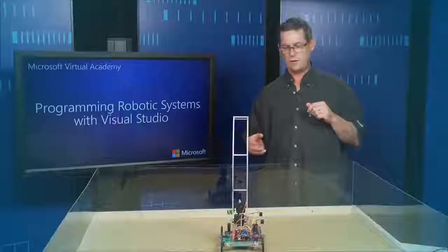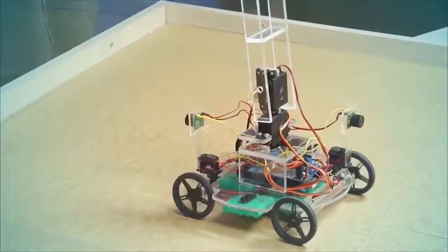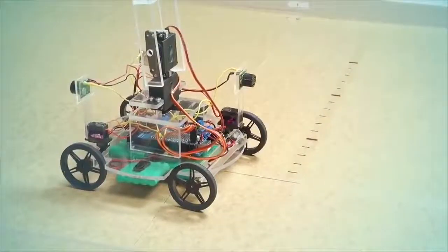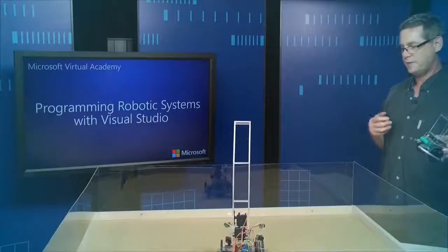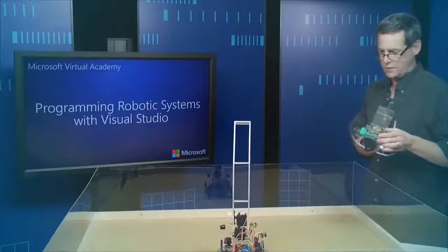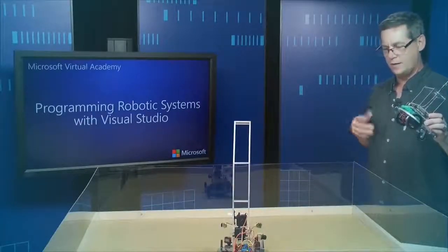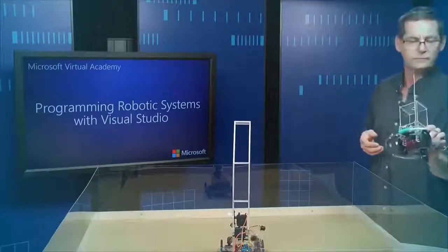Once he's moved to the center, he will start scanning the area for intruders. All right, a little bit more. I'm coming over here to our modified MS BugBot. So now you can see he's moving the scanners around. He's scanning the area, taking discrete readings at about 30-degree increments that we programmed in. Now, he knows what the distance is for the perimeter wall. If he sees something that's significantly closer than that perimeter wall, he's going to move after it.